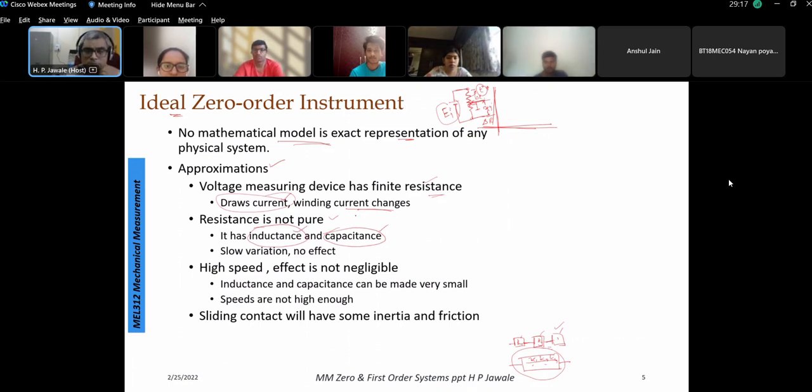Now, the variation is slow. Variation in the resistance is going to take some time for arriving at the proper, say, output EMF. So now if we are going to make it dead slow, say for measuring the distance of say 2 millimeter, if I am going to take say 10 minutes, very slowly I am going to move, then it is not giving any proper output EMF, right?